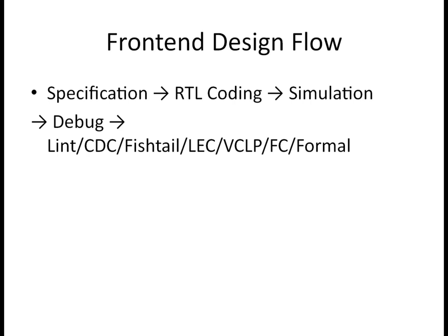And once this setup is done, we'll run this tool, Fusion Compiler, and we will convert our RTL to a gate level netlist. Okay, so these are the tools that the front end teams are using in mostly all the companies, and we'll make sure the gate level netlist will be handed off to the backend team.